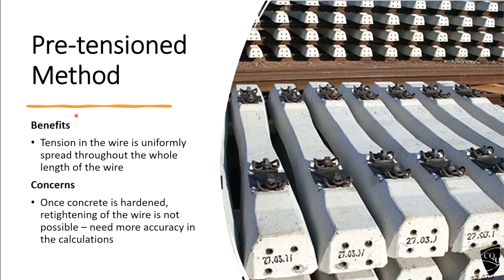Okay, so that is a good thing because it's uniform force. The problem is once you put the concrete, you can't change it. Once you put the concrete, you can't change the value, so you can't stretch further. Let's say you need to apply 20 kilonewton but by mistake you applied 15 or 18. That's it, you can't change it because the concrete is hard, so the steel will not move. So that's a problem.